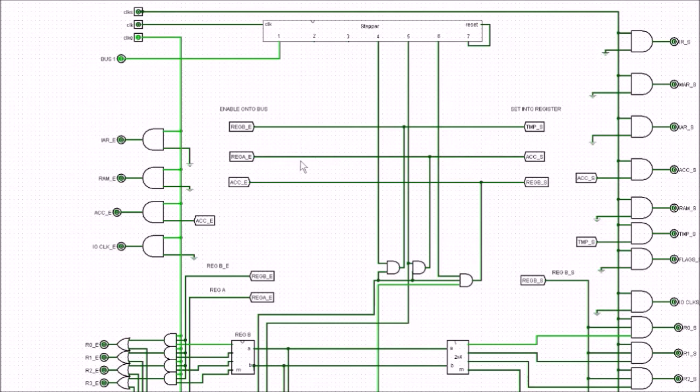Now the point that we want to take this copy is whenever the accumulator gets set. So whenever that accumulator gets set, we could take a little output here and connect a pin onto it. That'll be an output pin there, and that would be our set pin. So we could take this output and feed it into our little flag register, and it will take a copy of the flags from the ALU at the right point in time.